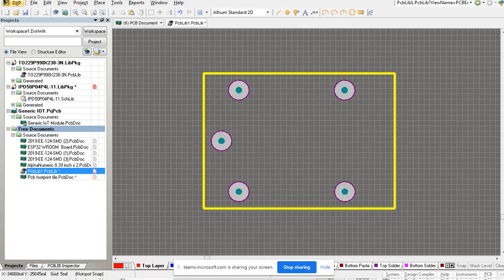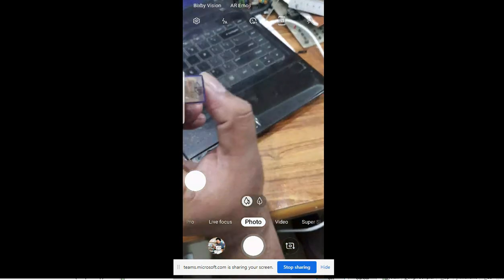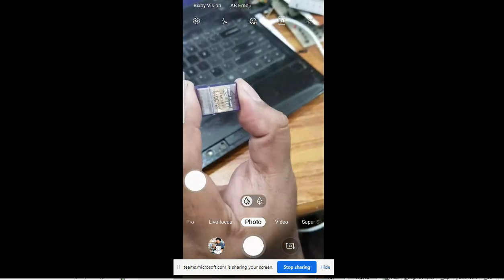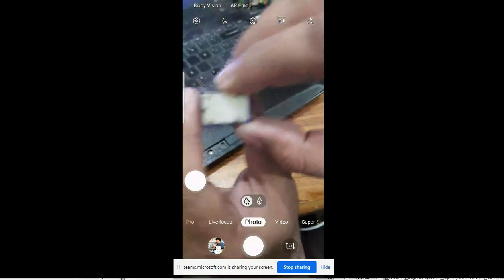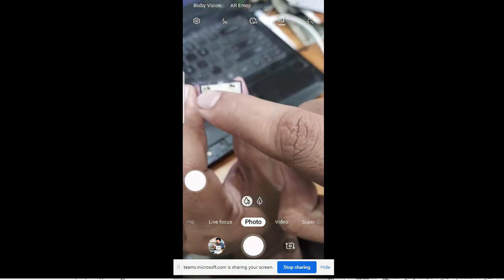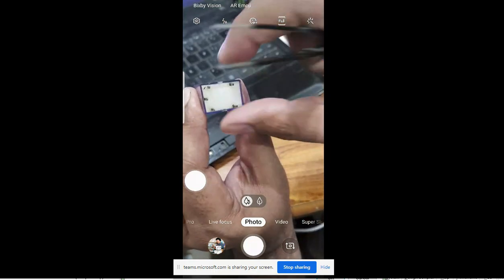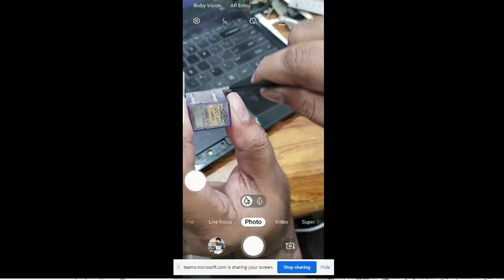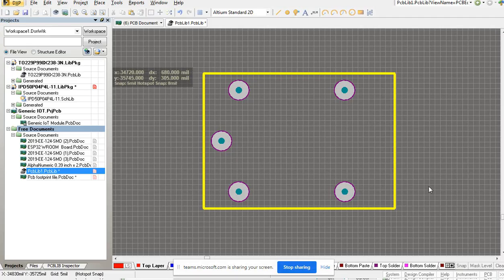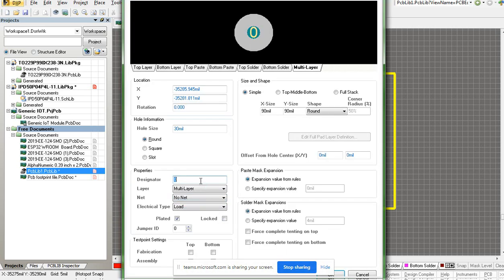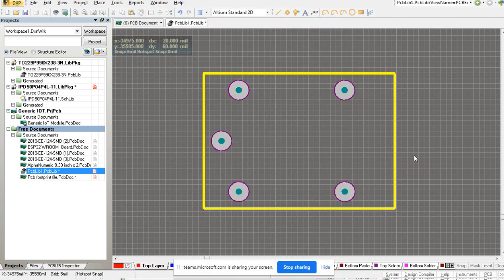And then when you are holding this over here, I hope everyone can see this one. When I am going to use this PCB, these pins are at the bottom, and as I just told you, when I was holding this, this one was the common pin, this one was the normally closed pin. So when I turn this round, the common closed pin comes here. So when I go back over here, this is the normally closed. Now here I will write NC, and here I will write NO, which means normally open. Normally means without energization, what happens. So I have now marked everything.